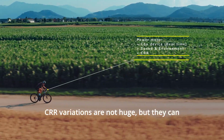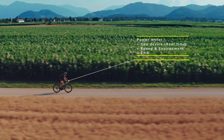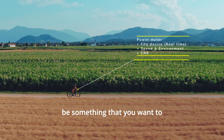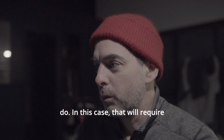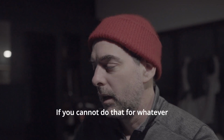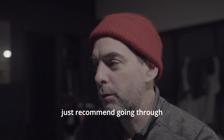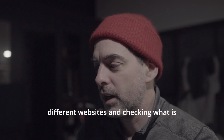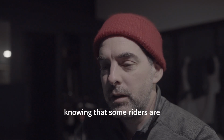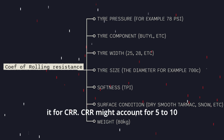Now, CRR variations are not huge, but they can play out among a few watts. So looking at optimizing CRR this way is really for advanced cyclists. However, it might be something that you want to do. In this case, that will require testing, which is something that I do, testing outside. If you cannot do that for whatever reason, then I would just recommend going through different websites and checking what the estimated CRR is, knowing that some riders are different weights and the tires might react slightly differently. In a minute, that would be it for CRR.